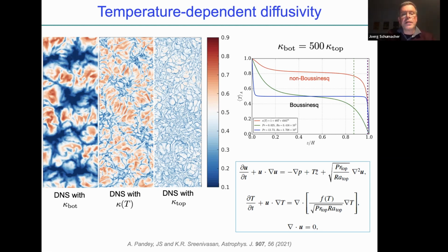And for those kind of simulations, it was really advantageous to have the spectral element method, because we were able to put many spectral elements close to the top surface and could provide a very asymmetric element spacing across the convection layer.